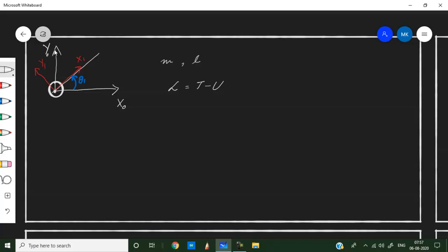And the equation of motion is given by d by dt of dou L by dou theta dot, minus dou L by dou theta, is equal to the torque. All right, so we are supposed to get something like this: M theta double dot plus h plus gamma is equal to tau, which is the equation of motion in a kind of state space form.